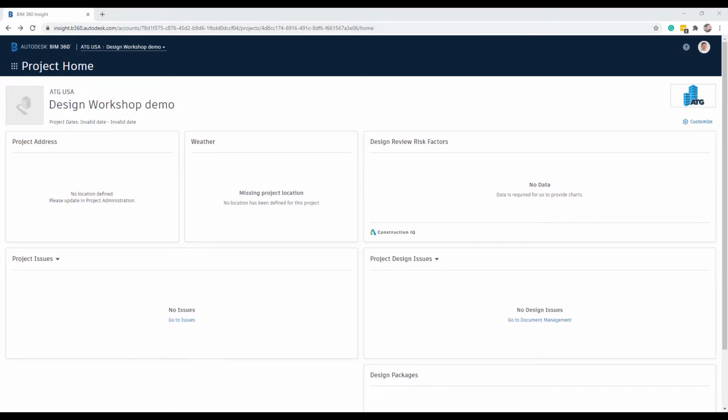Some things I want to teach you on this one: this allows users who are not actively working on a Civil 3D project in BIM 360 to get access. It also lets people do markups. It also lets people view projects, whether it's in PDF or a drawing file. And it lets you see who has things locked out, what kind of version controls there are, and things like that. So let's talk about this page right here.